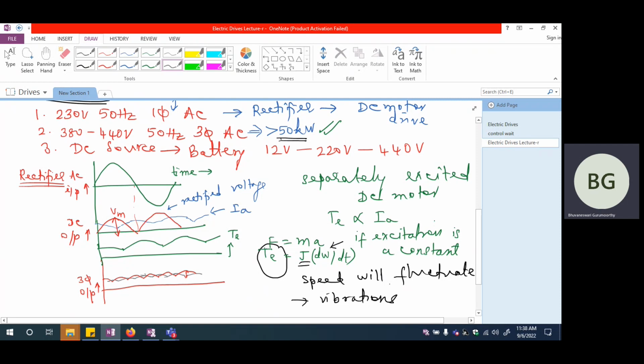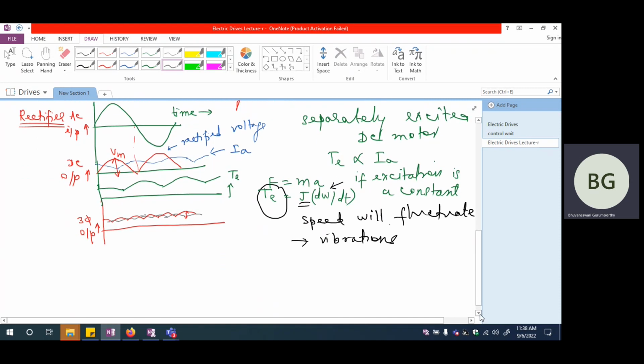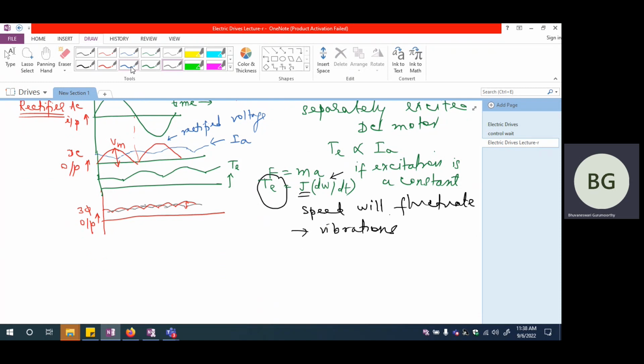And that is one reason why generally you're going to see that three-phase supply is generally employed in most of the industries where the total load capacity is greater than 50 kilowatt. Whereas single phase is employed in most of the industries which are small scale industries whose load will be anywhere close to 10 kilowatt or even lower. But single phase is employed in one case as an exception where the capacity is greater than 50 kilowatt. So one exception for this generalized rule is electric traction system.